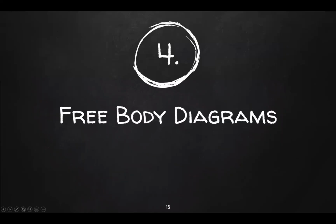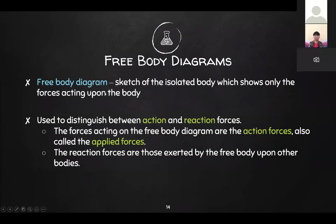Now I've mentioned free body diagrams. Let's talk more about that. A free body diagram is a sketch of the isolated body, which shows only the forces acting upon the body. It is used to distinguish between action and reaction forces. The forces acting on the free body diagram are the action forces, also called the applied forces, while the reaction forces are those exerted by the free body upon other bodies.